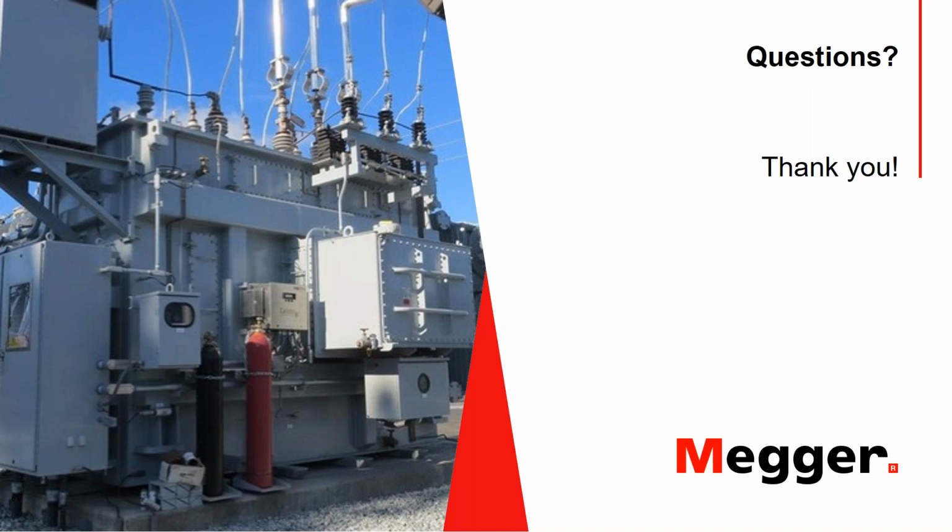But, and I think Samir briefly covered that in the beginning, the focus of the webinar was case studies, not so much on the theory. But remember that when you are performing this, the inductance of the transformer plays a big part, right? When you are injecting the current to take the measurement, you're pretty much storing energy, right? And that has to do with the time that you have to wait for the current to be stable so you can take an accurate measurement.